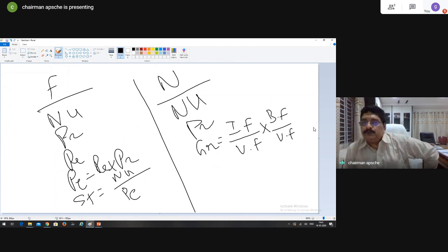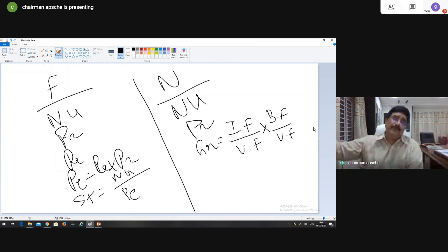So it is viscous force squared in the denominator, right? Inertia force to viscous force is the Reynolds number. And you will be surprised, in forced convection there is the inertia of the fluid molecules. Where is the inertia in natural convection? The fluid is not moving, only the molecules keep moving up and down, and there also you come across inertia.